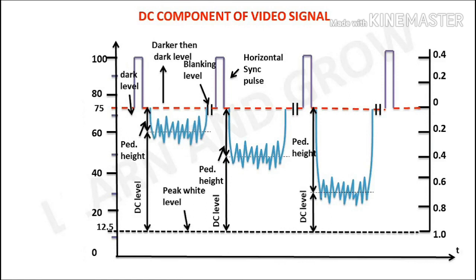Note the position of the first equalizing pulse at the start of vertical blanking in figure 7.7. In the signal at the top, the first pulse is a full line beyond the previous horizontal alignment pulse in the signal below. For the next field, the first pulse is half a line away. This half-line time difference between the even and odd fields continues through all subsequent pulses, so that vertical alignment pulses for successive fields are timed for interlacing odd lines.